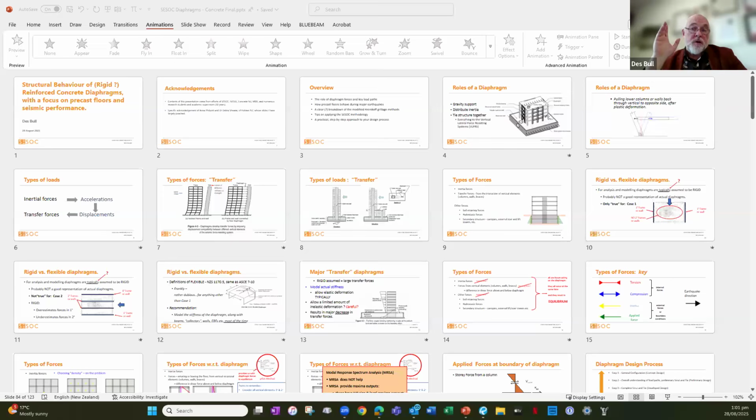The problem is on high drift buildings or low seismicity buildings, you find the PGA ends up being up the whole side of the building. This gives an artificially high lateral load to the problem of working out diaphragm load. So there is a problem, and that's being worked on. That's where I'm going: I don't have a solid answer for that question.